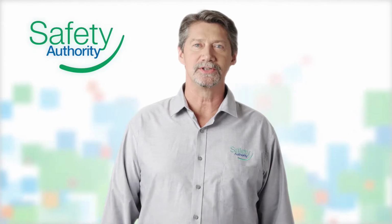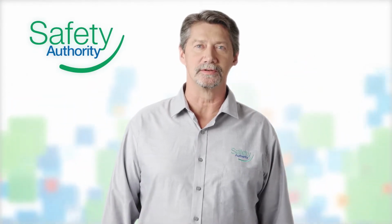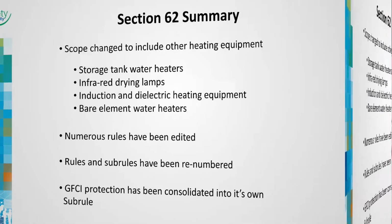We've come to Section 62, Fixed Electric Heating Systems. Let's see what the changes are for 2015. The scope in Section 62 has been changed to include other heating equipment. Numerous rules have been edited. Rules and sub-rules have also been renumbered. GFCI protection has been consolidated into its own sub-rule.